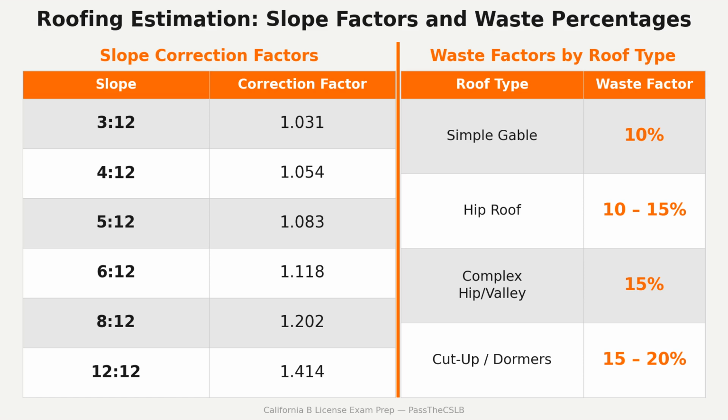Reverse that sequence and water tucks behind the metal flange, wicks backward into the fascia board, and begins a rot process that is invisible from the outside until it is already significant. The homeowner calls. You cannot find the source from the roof surface because everything looks fine from there. It is the eave sequence that was reversed. Add the rake, the sloped gable edge: underlayment goes down first, then drip edge is installed over it.